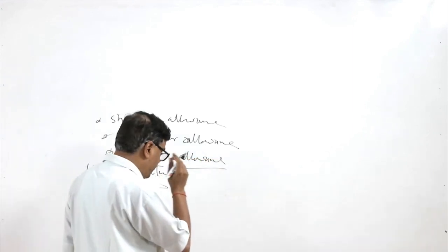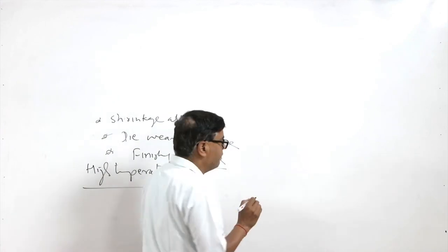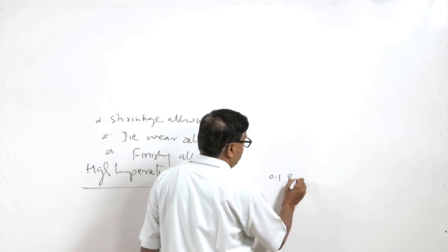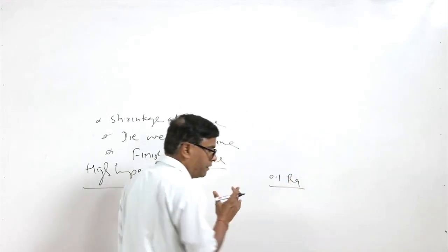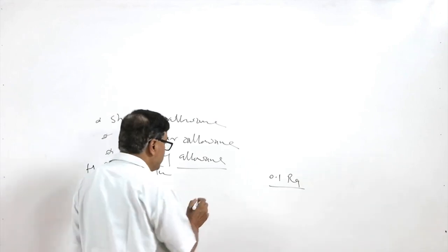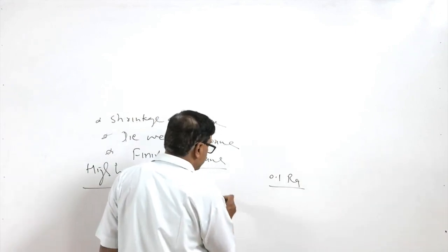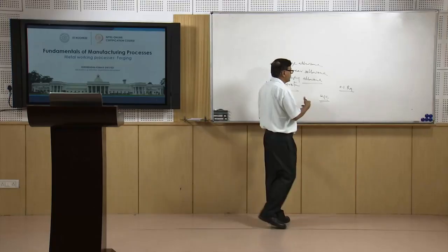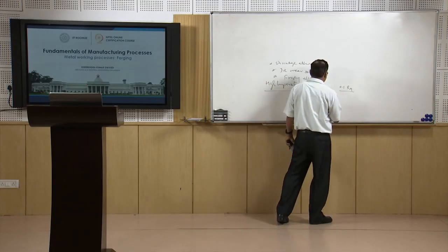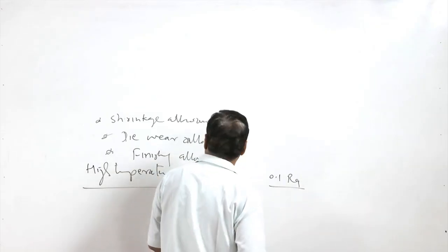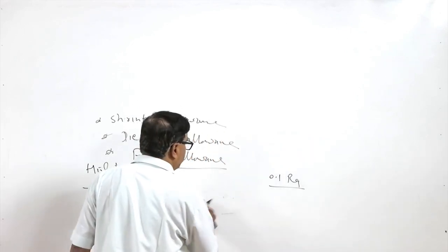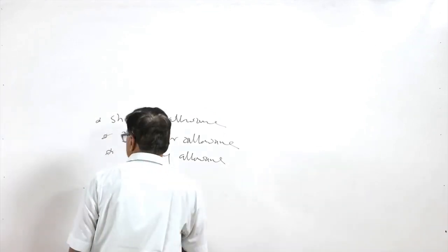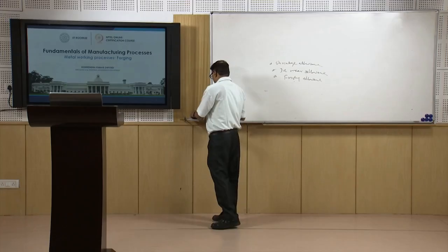We know that if you want a very good surface finish, like 0.1 Ra, which of course cannot be achieved through metal working processes, we need to machine the surfaces. For machining the components, we need to have the material. So, additional material is provided for the machining purpose, so that the desired finish can be achieved, and this extra material is provided by giving the machining allowance. So, these are the additional features related to forging.